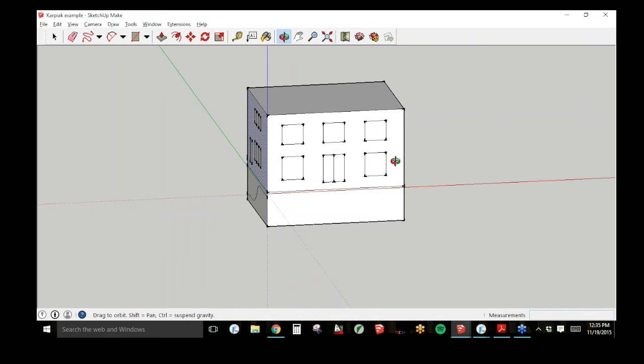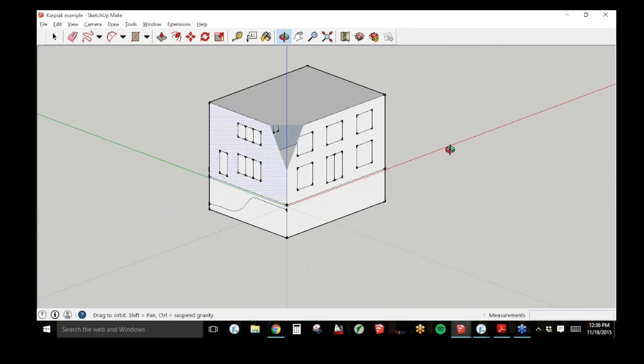If you're in the static model, you're going to get overall building results. It's going to combine the heat loss and heat gain from all of the zones, and you're going to get whole building results. Zones come into play when you're looking at the dynamic model. Then you can model and simulate all the temperature conditions and different mechanical systems in different zones.